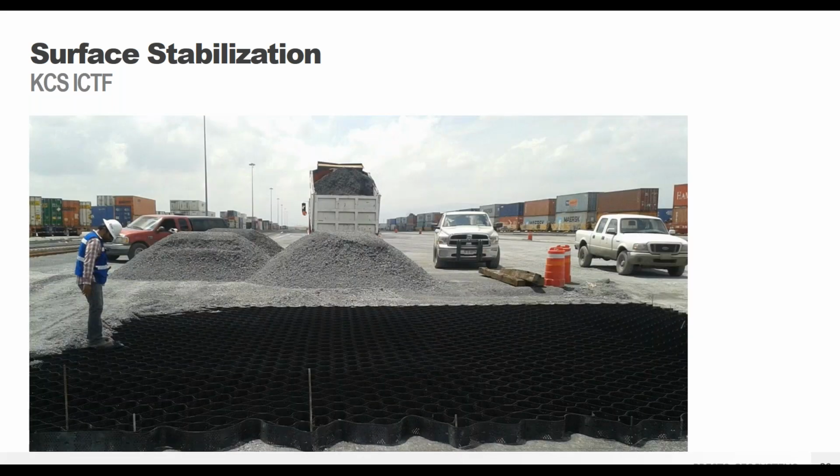But so you can see the GeoWeb panels, in this case, were being filled in with a crushed limestone, and they were able to keep the fines relatively low. There was about 10% fines in the stone, so that they were able to have some storage of stormwater and keep that ability to infiltrate water into your subbase. And so this is just a great photo to show that infilling process.